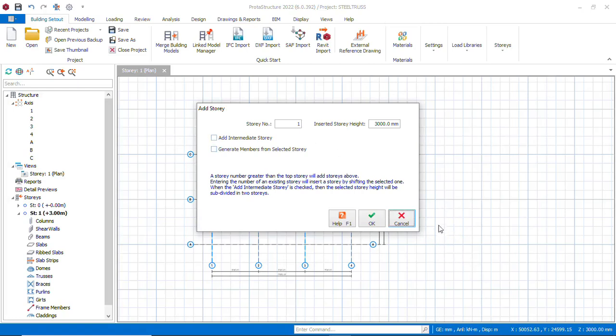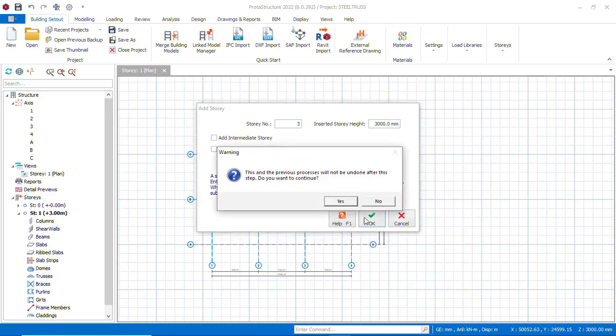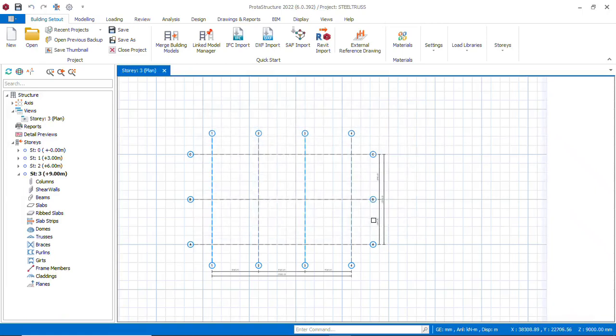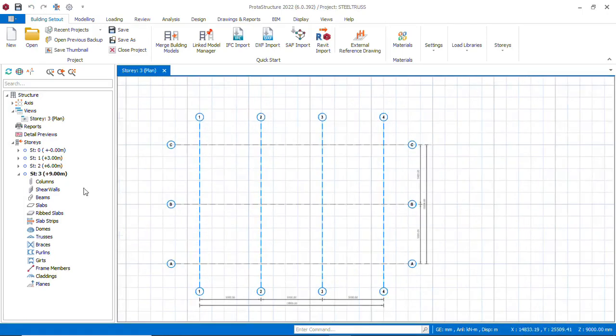The second story will take care of the steel that is 3 meters, and the third story will take care of the steel column that is 4 meters. So we'll enter 3 here. It's a story height, so we leave it by default, 3 meters. When you enter this, you see automatically it has taken us to the third story. Okay, ticked. Come here, edit story.